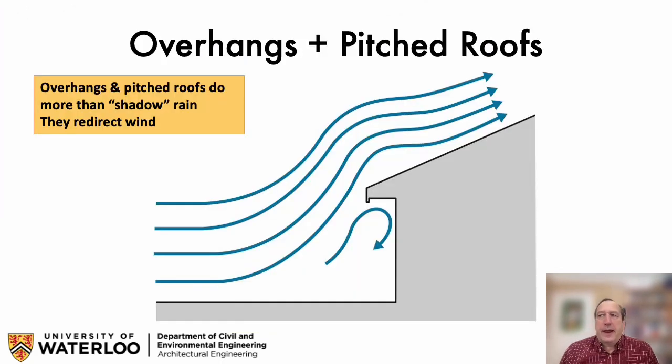An important and often overlooked factor: before, I would say, 2000, modern design, even in the building science world, didn't really talk much about pitched roofs and overhangs as a rain influencer. There's been a lot of research in the last 20 years to investigate this, and by now we have really good confidence that they can make an important difference.